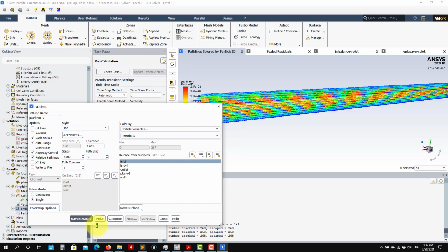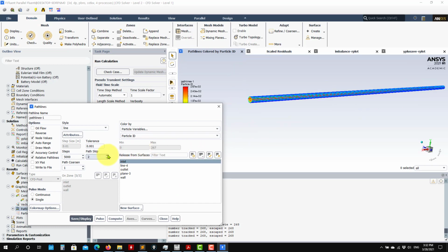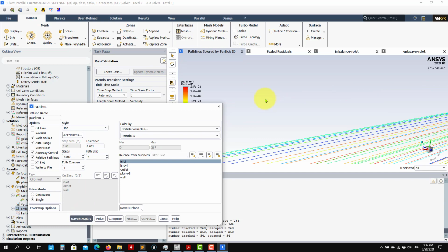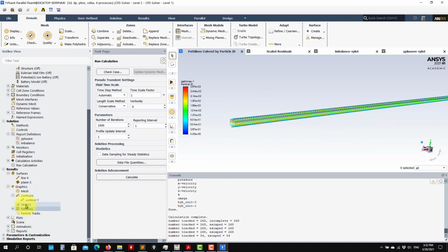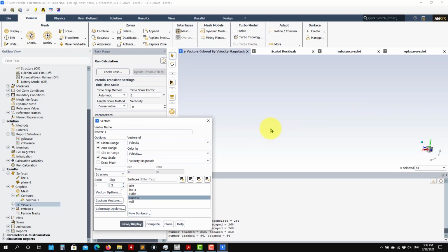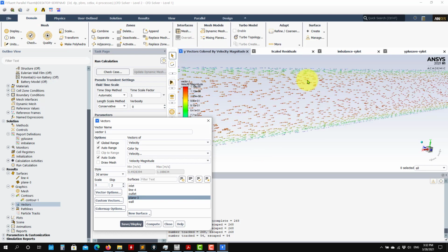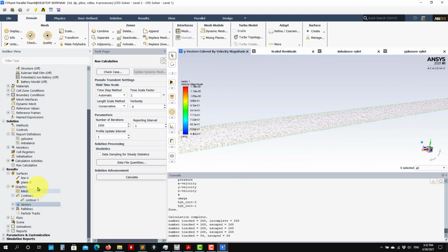Again, be careful, because if you have very large meshes and you put all the streamlines, it's likely that it will crash. So always play around, put a large value there, and then start to adjust those values. Vectors will be the same as I mentioned. So vectors, you are going to put in the plane. Do not put them in the volume because it will likely crash. So let me skip 2, and then you put it there and see that you have your vectors there. Nice vectors. Okay, particle tracks, for the moment we are not going to work with that.